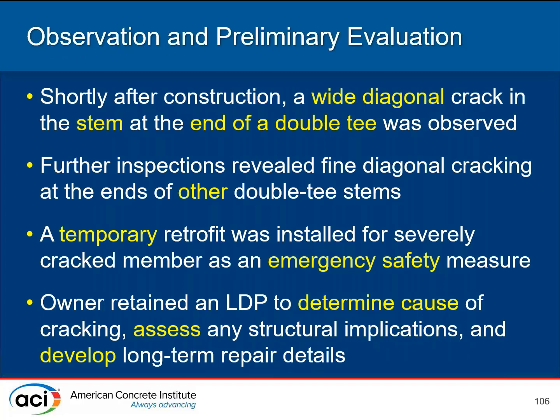And a large number of water tanks. Shortly after construction, someone saw a crack. That motivated a whole bunch of, we need to do something. They found this one big crack, and a number of the other double T's had fine diagonal cracking. That obviously pressed the panic button. A temporary retrofit was installed as emergency safety for that big one, and then a licensed design professional was retained to follow the 562 process, determine the cause, assess the implications, and develop the long-term repair.